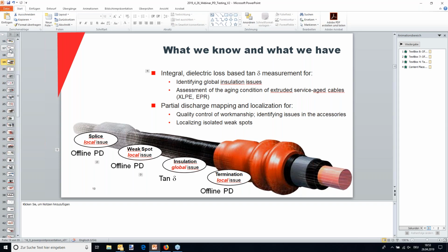That's predominantly the application. It has various accessories, test sensors, transient earth voltage sensors. It has the acoustic parabolic. It has the capacitive sensors and all of these sets. And that is mainly for medium voltage switchgear, fairly low cost to keep it attractive.